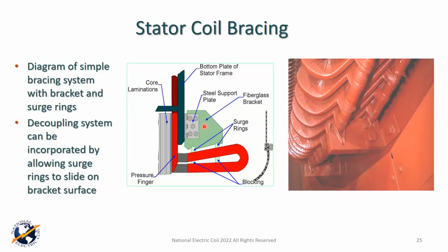And when we talk about the way machines act thermally, this coil, when it grows, it tends to grow axially. So the length of the coil is going to want to extend out of the slot, okay? And when it does that, if you try to restrict it a lot in here, things are going to want to buckle and do things that we don't like. So there was a period of time with designs where they made some where they had that and they said, holy cow, we're having a lot of problems with those forces that are in there.